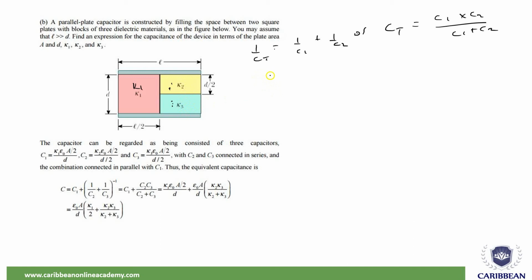So with that being said, we could have found the capacitance of those two capacitors in series. Then we would be left with this thing here. So let's see if I can redraw the plate. By way of redrawing this, we now have two capacitors. This CT would have told you the capacitance of this capacitor. Then this K1 here is giving rise to another capacitor that is now in parallel with this one. So in total, you have two capacitors that are in parallel with each other.